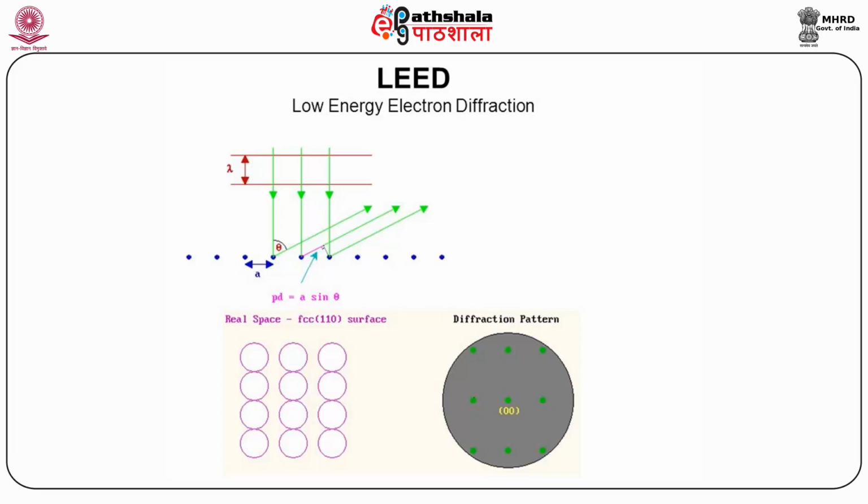A different approach to prepare well-ordered nickel oxide film was used by Marre and Neddermeyer, who evaporated nickel onto a gold-silver surface in an oxygen atmosphere. LEED and UV photoelectron spectroscopy have shown that a well-ordered and smooth nickel oxide can indeed be obtained in this way. The reason for this more perfect growth of nickel oxide layer by using a gold substrate is the smaller lattice mismatch between nickel oxide and gold.